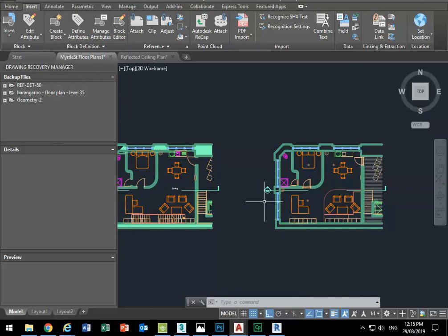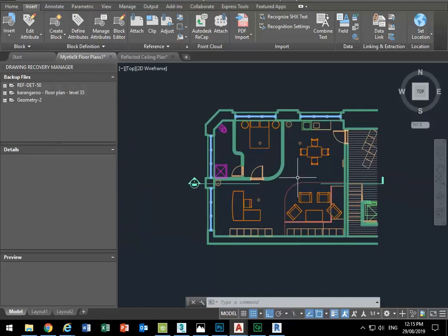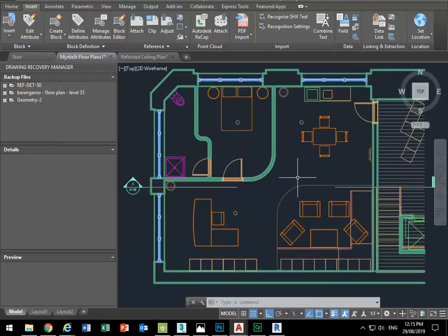Everything on your ceiling. So lighting, emergency services, air conditioning, they're the main things. Now, it's easy because you don't have many emergency services for an apartment. There's one big one. What do you think the main alarm type thing you have in residential? Fire, yeah? Or what's the other word for it? What's it detecting? Smoke. Smoke alarm. Yeah, that's it. So smoke alarm detection or detection alarm system, technically.